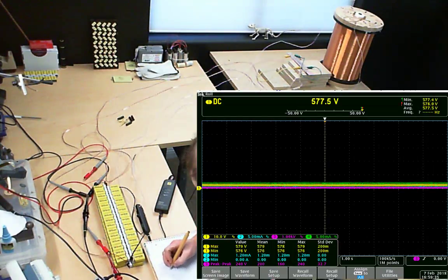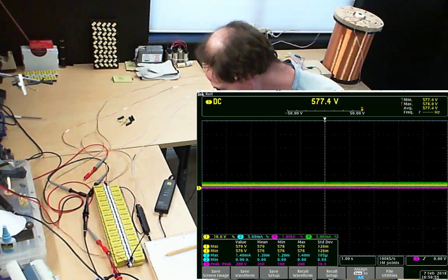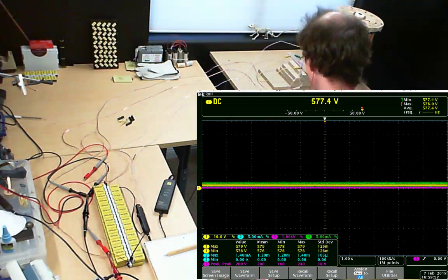I think that's just the difference in the calibration of the two instruments. Well, I think it's actually the noise on my probe, because it's not supposed to be reading this tight tolerances. Which actually is pretty good, because on the 6,000 volt peak to peak scale, it's huge.